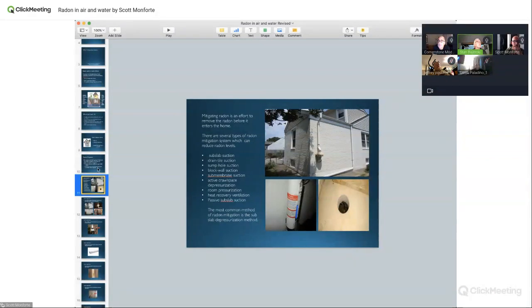Now, that's a good question, Stan. It's to cover, correct, because you can't suck through dirt. There are some waterproofing companies out there, won't mention their name, that sometimes to waterproof completely, they'll cover the concrete and go up the walls. In that case, it's still sub-membrane, but it's on top of the concrete, or I may actually drill through the concrete and seal the plastic up. Sometimes they just want it completely waterproof. They might have a little sump in the corner. But yes, most of the time it's covered with plastic, with a moisture barrier.